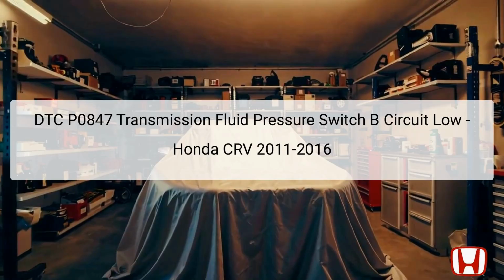The diagnostic trouble code, DTC P0847, indicates an issue with the transmission fluid pressure switch B, specifically within the third clutch circuit. This DTC is categorized as a circuit low fault, meaning that the electrical circuit related to the pressure switch is not operating within specified thresholds, leading to potential gear shifting issues. The transmission fluid pressure switch plays a crucial role in monitoring the hydraulic pressure in the transmission, which is vital for the proper function and shifting of gears.